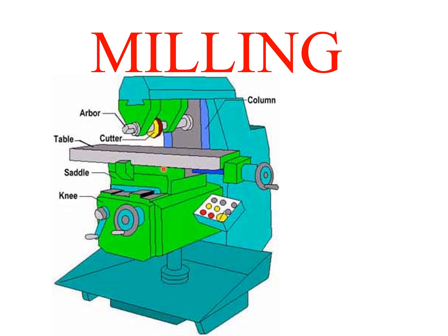Too low or too high a cutting speed will cause the tool life to decline dramatically. Meanwhile, in the milling of thin-walled workpieces, spindle speed of revolution has a significant effect on the stability of cutting. Therefore, the spindle speed of revolution should be selected carefully in the milling process.